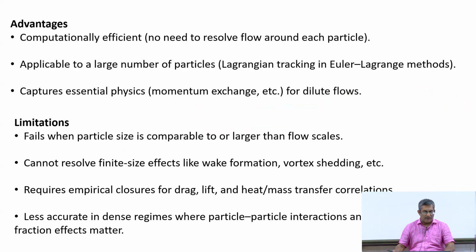However, if the particle size is too large and that causes vortex shedding, there is no model which can correctly account for that. So, for such cases, if the particle size is large, we have to adopt a fully resolved simulation approach only. What are the advantages and limitations of the point particle assumption?